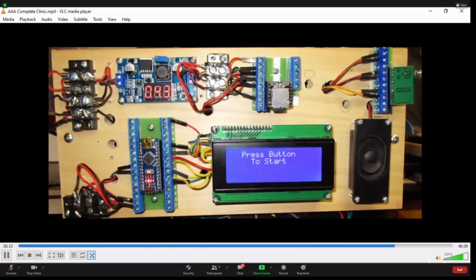To control the lumberjack, I ran a wire from pin 2 of the expansion board to the control wire of the servo. The other 2 wires, red and black, are for power and ground and should be connected to the output of the buck converter. A wire from pin 4 should be connected to the wire controlling the motor, which controls the tree.